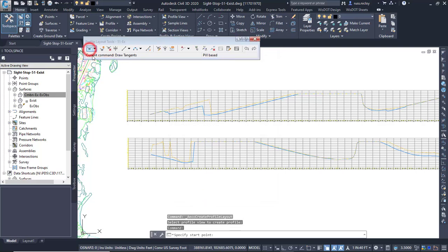I'm going to select this point here. I'm actually going to create just basically a straight line through here. I'm actually going to use the transparent command, the station elevation here. I'll select on the grid. I'm going to start somewhere over here. It doesn't really matter as long as it's before our project.